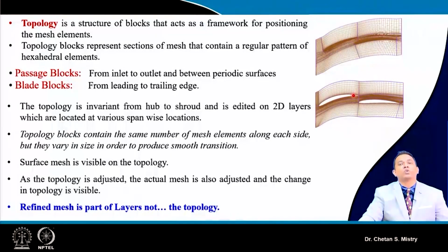Without blocking also you can do your meshing, but it is preferred when you are meshing axial flow turbomachinery, be it an axial flow compressor, axial flow fan, or axial flow turbine, that we adopt this kind of configuration. There are some commercial packages in which these blocks are made ready-made. With that understanding, even using other meshing tools, you can make your blocks and analyze the flow physics.